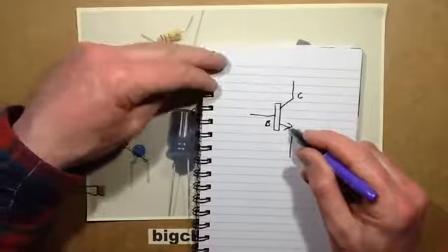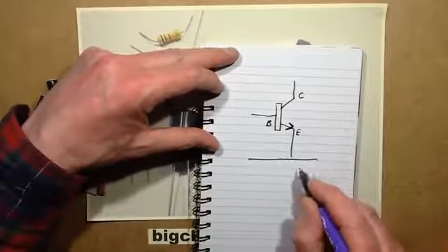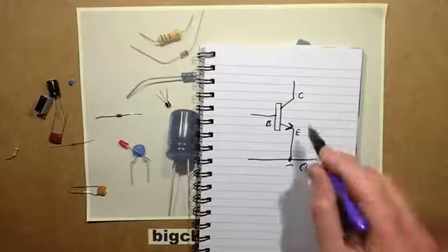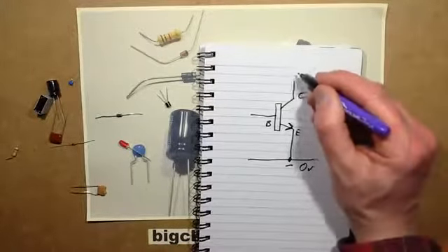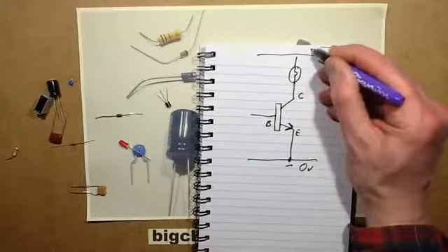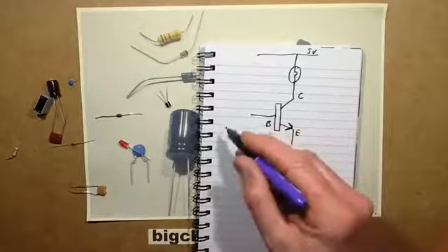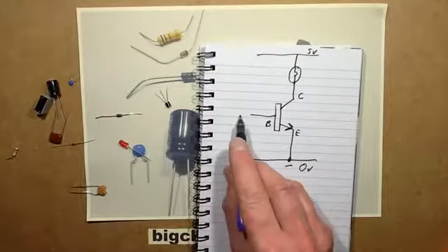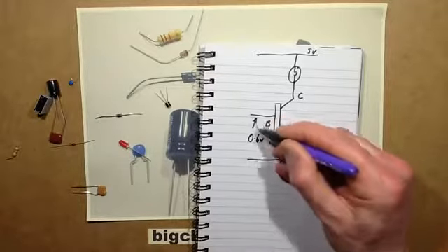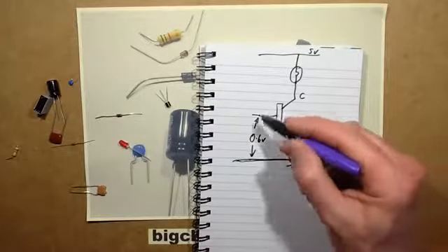In the case of an NPN transistor, it's usually switching something down to the ground rail, the negative rail, or the 0 volt rail. And it's used as an amplifier or switch. Supposing, for instance, you had a small tungsten lamp, and you had, say, a 5 volt supply. If you wanted to turn the lamp on and off, but you only had very limited current available, you can use a transistor, and as soon as you exceed about 0.6 volts, because it's silicon again, that's the standard silicon junction voltage, above the ground rail here, the 0 volts, and